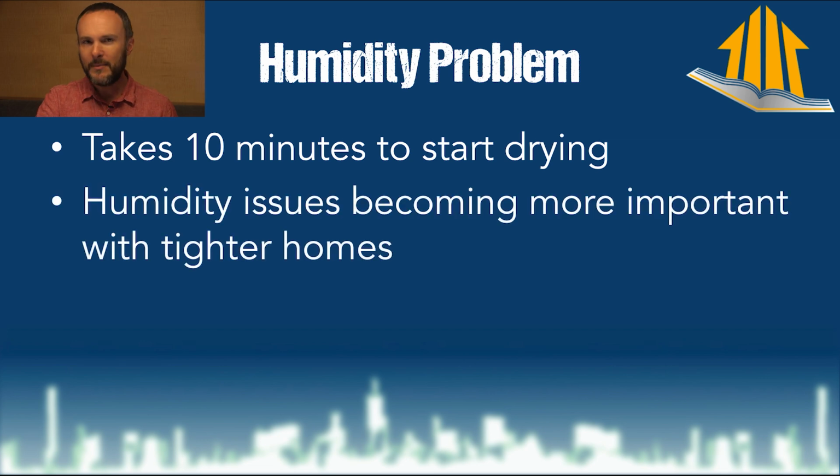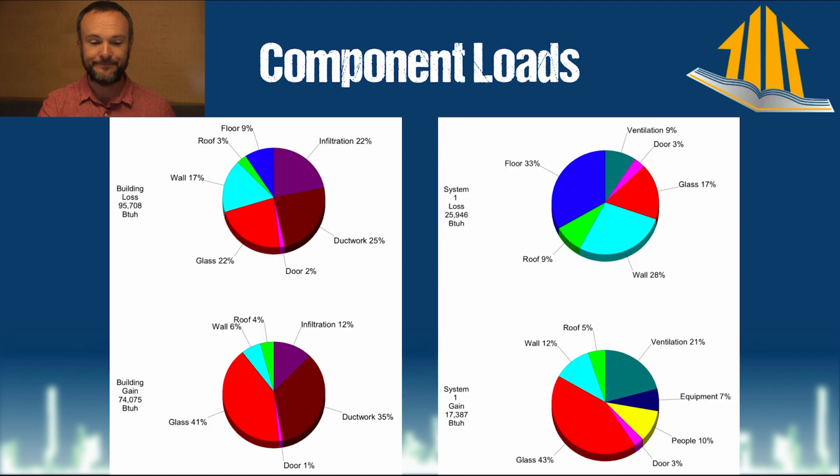So the humidity issues that we're talking about are going to be a problem as we keep building, because newer codes are requiring tighter houses, better insulated. We basically are making these houses very tuned for the enclosure. But if you are not actually enforcing the code requirement of load calculations, then we're going to have major problems with this humidity issue because we are going to have oversizing.